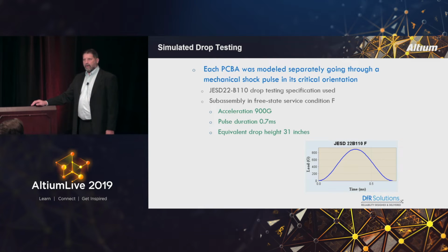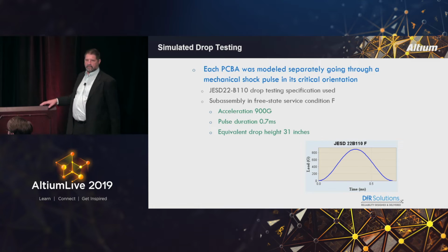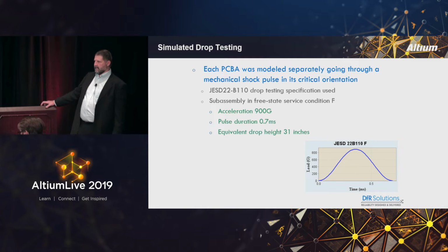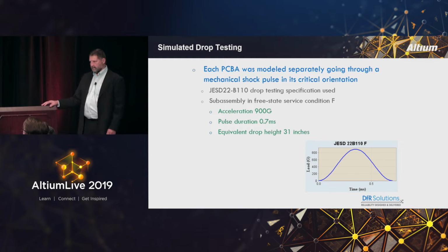That oftentimes will result in the highest stress that component is going to see. If you ship by rail, one rail car slams the next and it slams the next, and there's high G forces when that car gets pulled by the previous car. These are things you should consider when evaluating what kind of forces you need to be able to withstand.